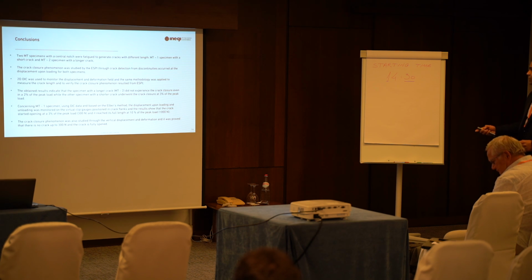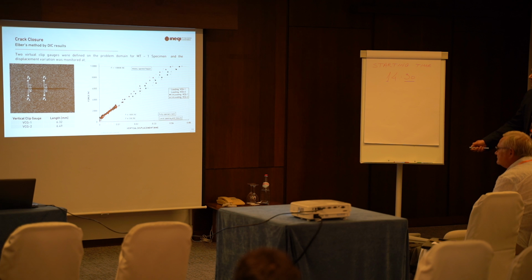But it was very close. And as a conclusion, with the 300 Newton, we have local opening and closure. It means that the crack starts to open and close in loading and unloading. And when we reach 10% of the maximum load, which is 1 kilonewton, the crack is already fully open. And once we load the specimen from 1K to 10K, this is the widely open region. It means that the crack has already opened, stabilized, and it is with the full region visible by the optical techniques.